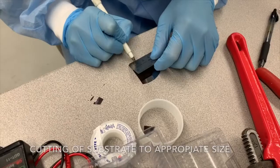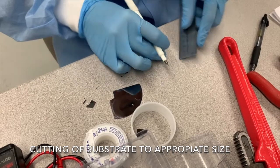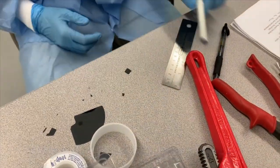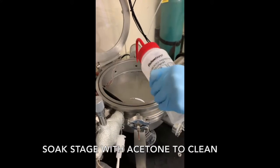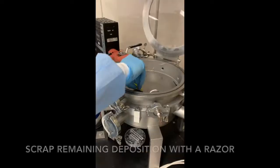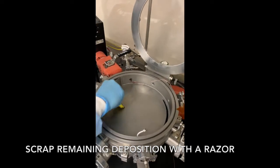energy. First, the substrate must be cut down to an appropriate size of about 0.8 cm by 0.8 cm. This is to be kept constant across the whole experiment. Next step is to clean the stage. First, you must soak it with acetone. Once the acetone has sat for a little bit, you can then scrape the remaining deposition with a razor blade off of the stage.